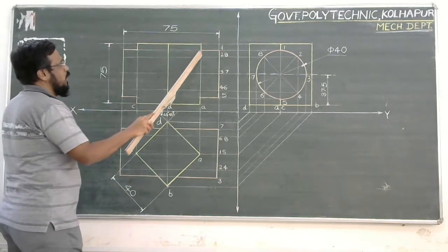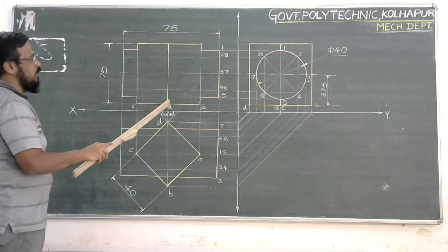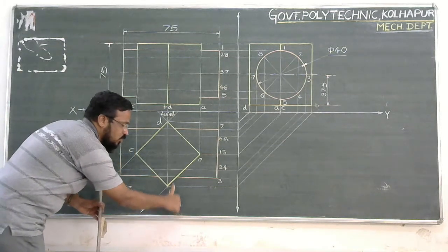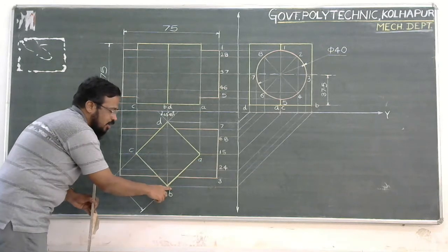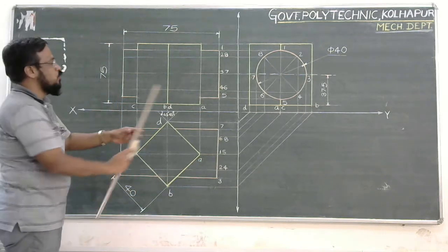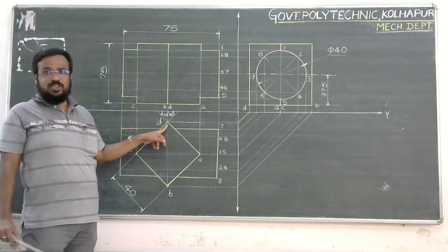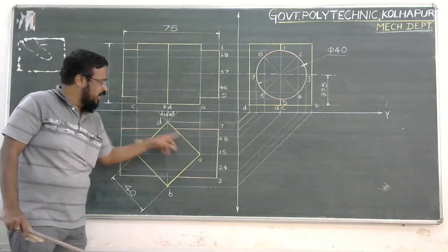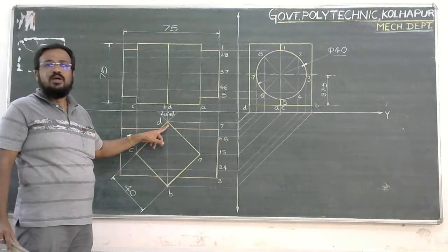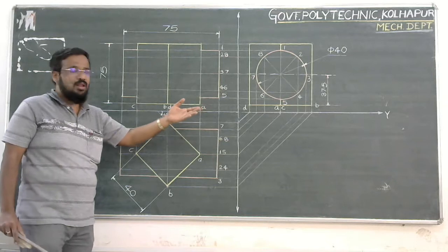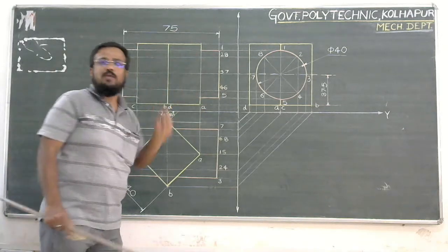So this portion clearly denotes the representation of this square prism in the front view, because the observer is looking at this object in this direction. When you observe this, he is well in position to observe the A to A dash edge, B to B dash edge and C to C dash edge. So A to A dash is visible here, B to B dash is visible, C to C dash is visible. Only D to D dash is not visible. But what happens, as this is situated with its base equally inclined to VP? That means exactly D comes at the backward point of this B. So D to D dash is not visible, but it is covered by B to B dash. So this way you can complete the projection of this square prism in the front.